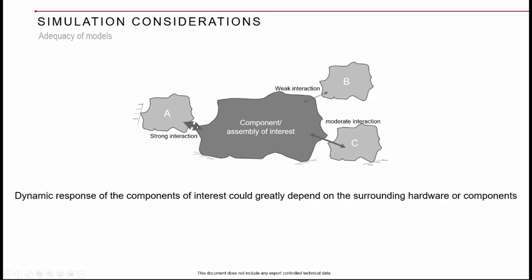But when you go and test it with all the hardware mounted, you will find there is a surprise for you, with a failure at the mounting location. Even the mode shape can be different, and you may see failure on your component of interest at the lug also. So it is always good to understand